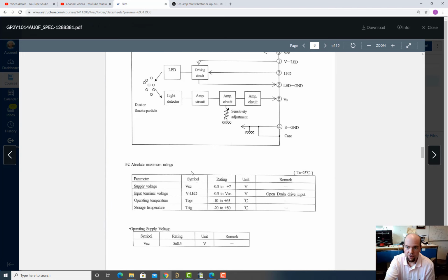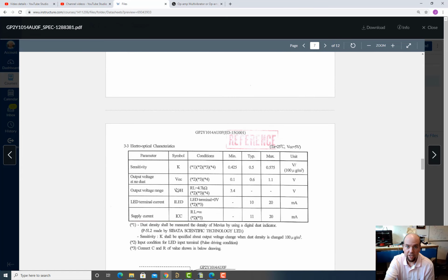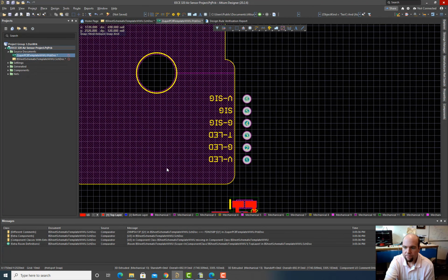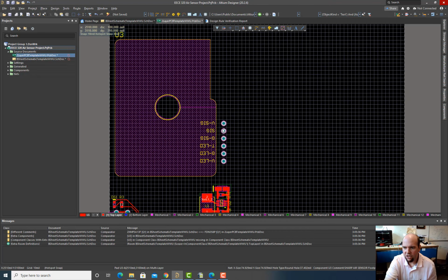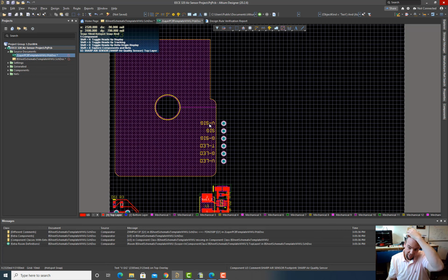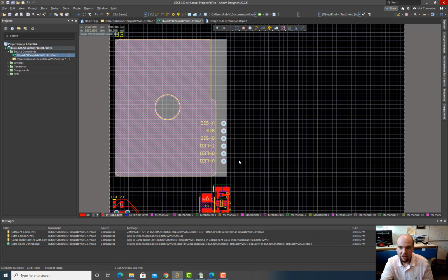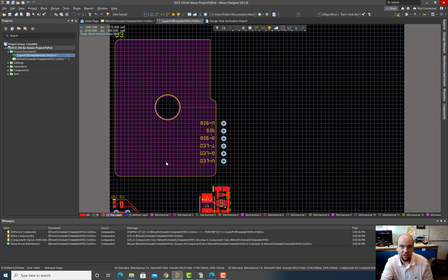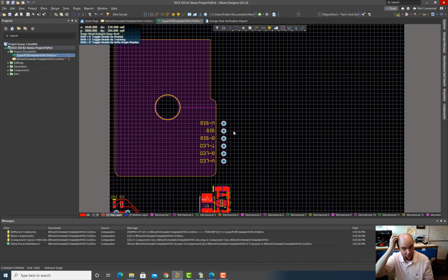You have a lab that basically goes over these topics, so I'm not going to spend too much time. We're basically just going to build it. But just to note, these little holes next to this sharp sensor, there's a little jumper connector and loose wires, and so you're going to have to manually solder wires to this thing. You connect the specific connector cable, but then take the stripped wires, feed them through these holes, and solder these manually. The nice thing about being through holes is you have a little more flexibility, in the sense that all that matters for the sensor is what's here. You don't have to use this footprint for the sensor as shown here, as long as you get those ribbons in the hole.